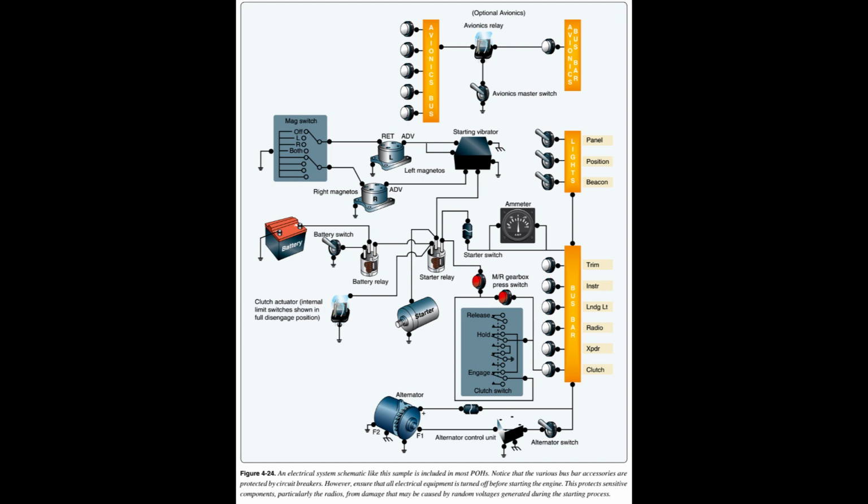An ammeter displays the load placed on the alternator or generator by the electrical equipment. The RFM, see page 5-1, for a particular helicopter shows the normal load to expect. Loss of the alternator or generator causes the load meter to indicate zero.